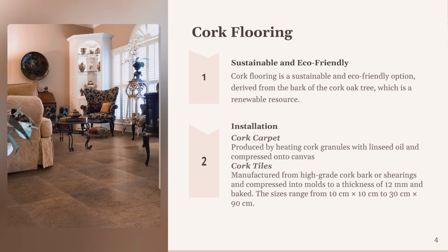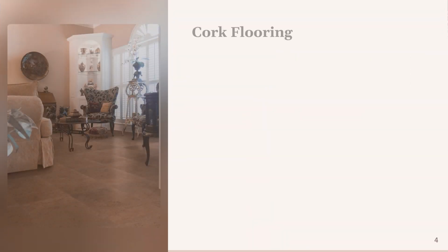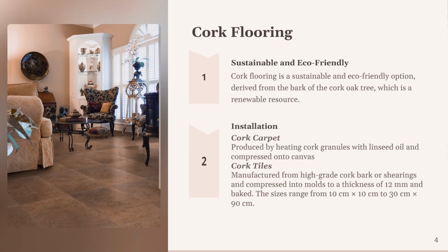Cork flooring is renowned for its noiseless properties, making it ideal for libraries, theatres, art galleries and broadcasting stations. Cork, derived from the outer bark of the cork oak tree, is available in the form of cork carpets and tiles. It is fixed to a concrete base by incorporating a layer of saturated felt.